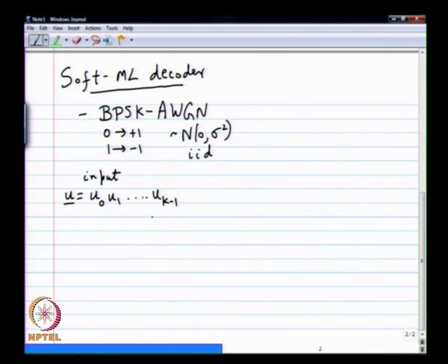These are going to get encoded into a code word. This is the convolutional encoder. I have this habit of drawing the box first and then writing inside, so what I write inside tends to get really cramped. Sorry about that. Anyway, I think it is clear enough. The encoder is going to put out now capital N outputs. We will always fix a rate half code.